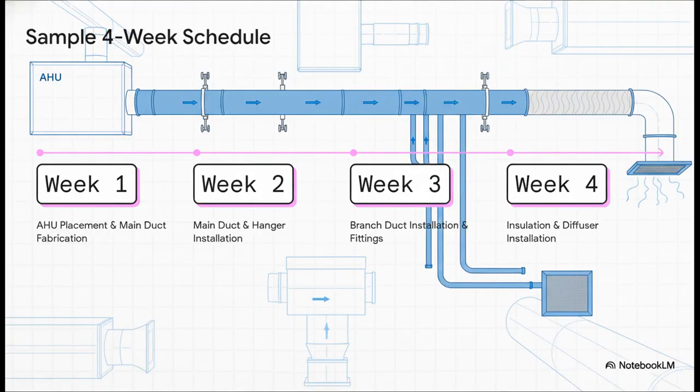So this is where we add that fourth dimension, time, to our 3D plan. By breaking down the installation sequence into a schedule, we can create weekly and monthly look-ahead plans. And this is what allows the site team to manage resources, manpower, and procurement so much more effectively.